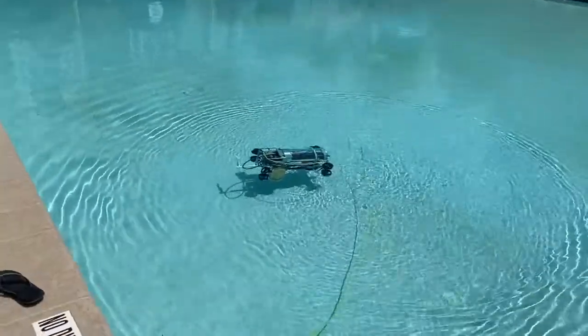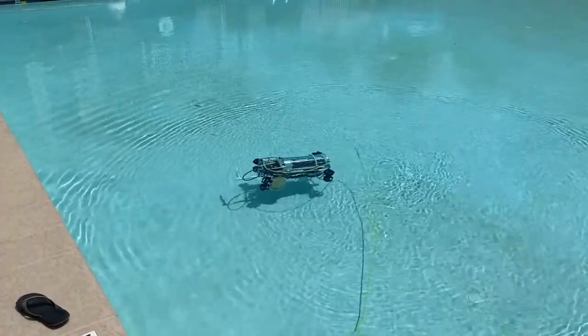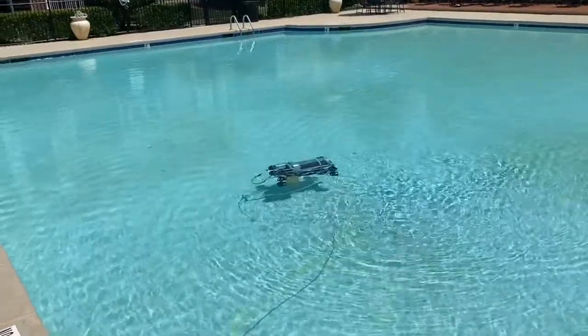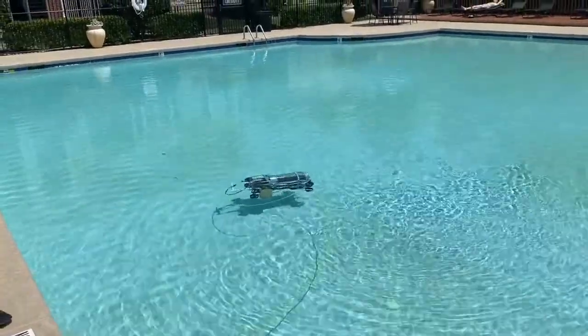Testing in person was important for validating our Arduino system's ability to tie everything together, because that's one thing we could definitely not test virtually. And it turns out everything works. All thrusters activated when the Arduino sent the signal, meaning the multiplexer system was working, and the power supply for the thrusters was sufficient. One concern we did have early on was that we had a few resistors in the circuit that overheated. However, we were able to resolve that by reorganizing and resoldering the circuit.